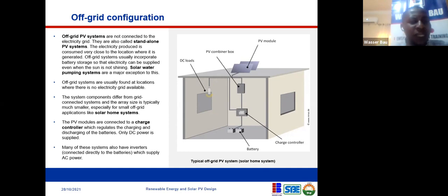So that's exactly what Chima is saying. The idea of the pumping is for you to save energy. Somebody also asked that question again, Engineer Ibrahim. During the day, you pump the water and store it in the tank. During the night, there's no light, there's no radiation, so it's not going to work. So water will come from the tank and you use it for your daily use. That concept is now being used in large-scale storage systems because we don't have large storage batteries, and pump storage is the future battery they are looking at.